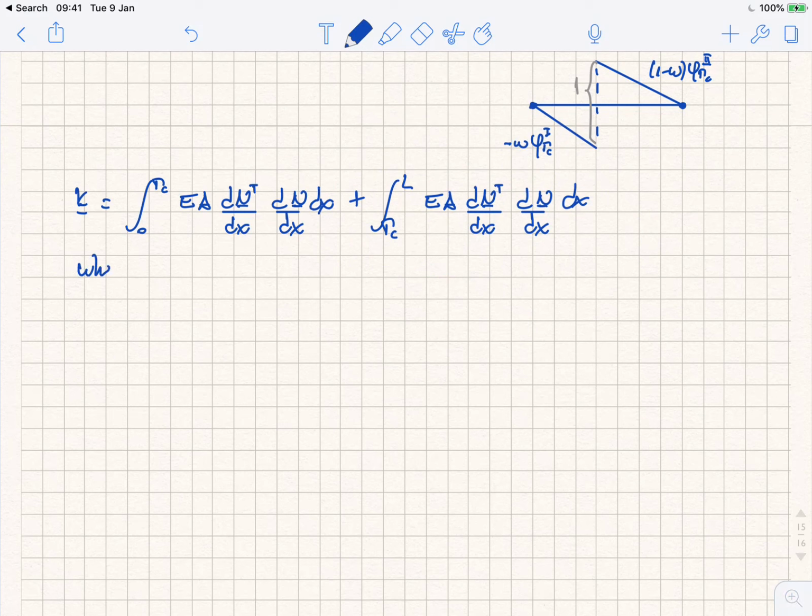Okay, and as in GFEM, the only difference that we make is to stack together the partition of unity shape functions, and we put the enrichments at the back. The same thing we discussed many times. Although there is a subtlety, and we discussed this last class, when it comes to the implementation, you have to deal with these two Jacobians as we discussed, okay? That is the only trick.